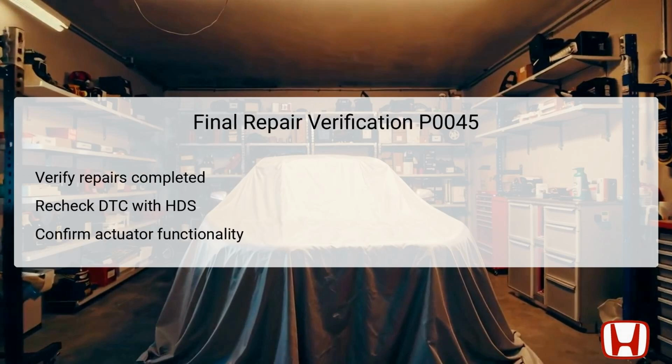After all troubleshooting and potential repairs have been completed, it is crucial to verify that the repairs were effective. First, reattach all connectors and ensure that the vehicle is properly assembled. Next, use the Honda Diagnostic System, HDS, to recheck for any DTCs. If the P0045 code reappears, this may indicate that further investigation or additional repairs are necessary.